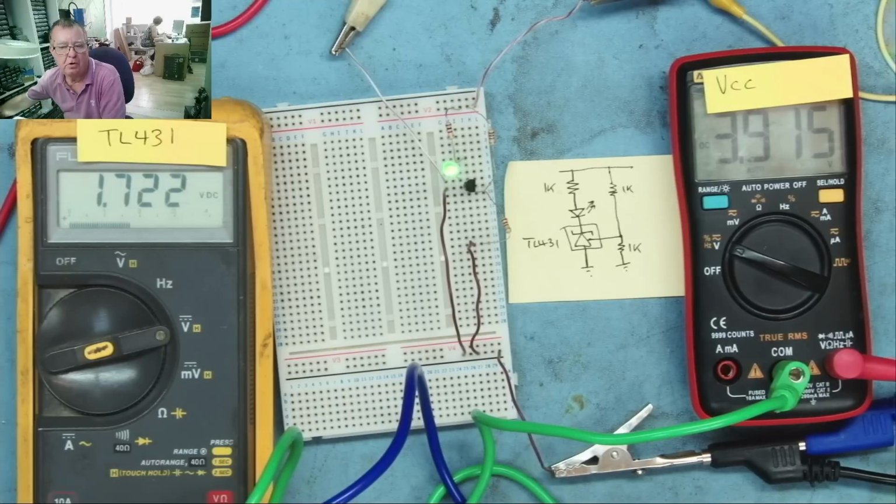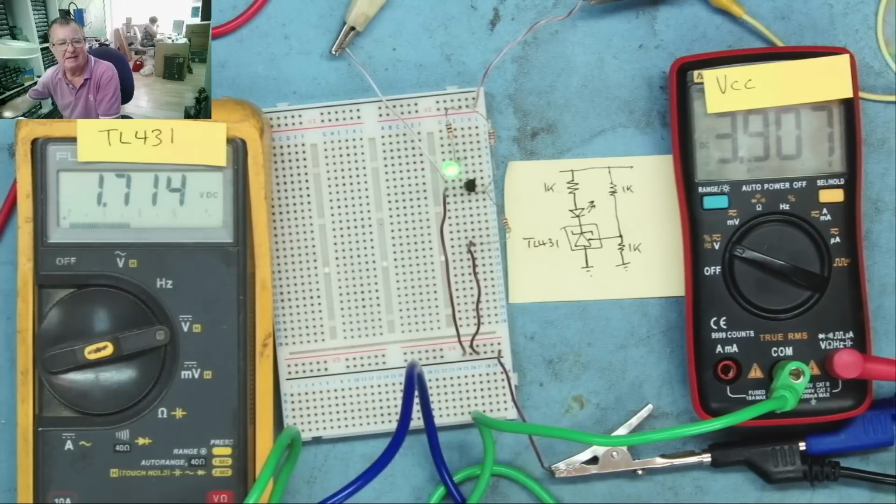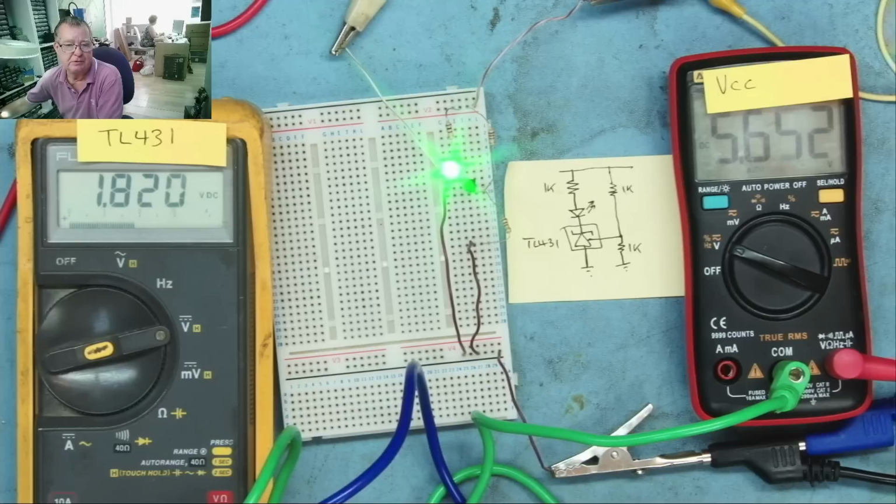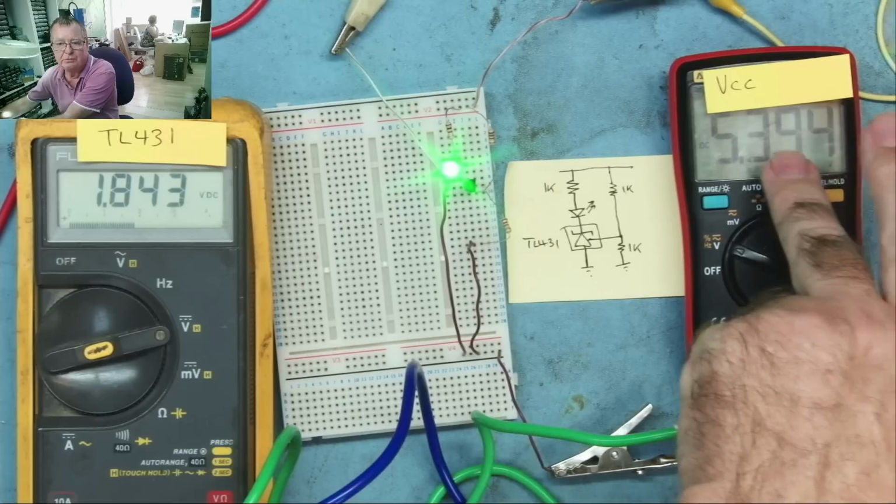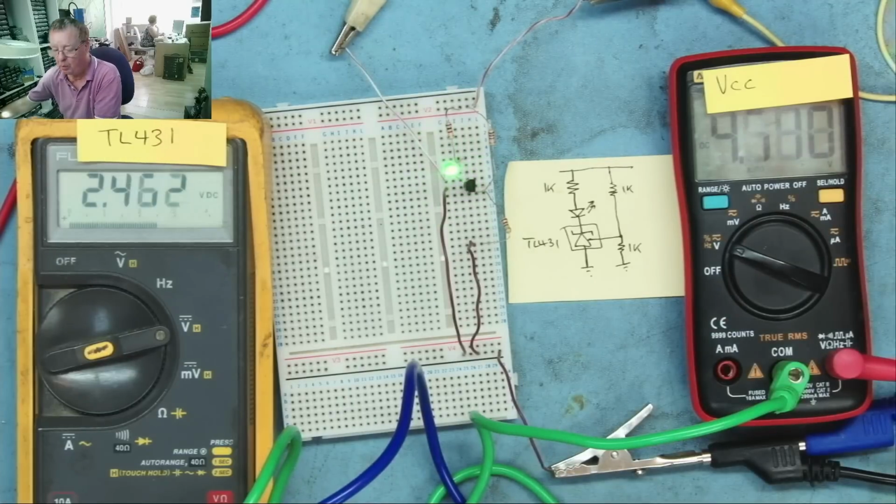Now, in the most common usage for these, or at least the usage we're looking at today, which is in power supplies, this LED is actually part of the opto-isolator. And that's what signals to the pulse width modulator. That's the chip that is generating the power in the transformer that generates the output voltage. This signals back through the opto-isolator to tell it to back off. You've now reached 5 volts on the output, or whatever value you set using these resistors.